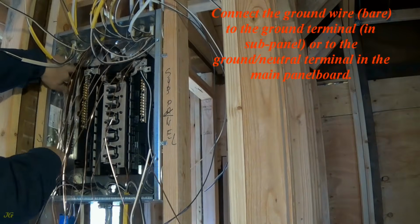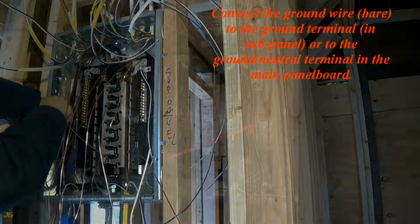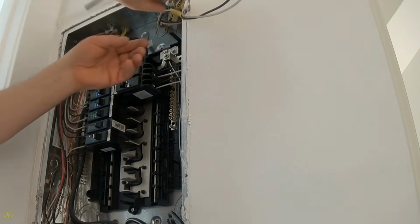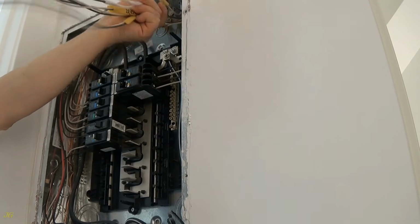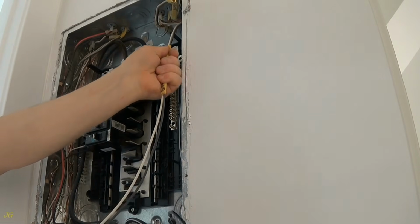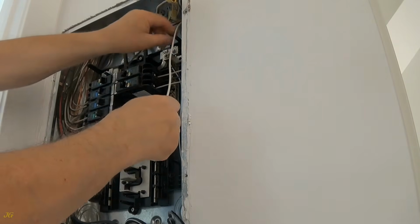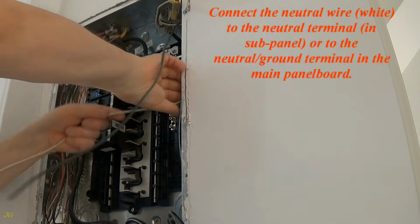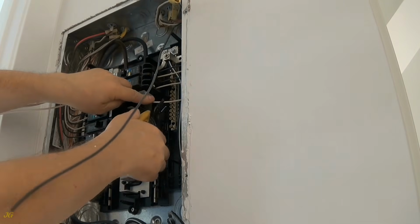Connect the ground wire, bare, to the ground terminal in a sub-panel, or to the neutral, ground terminal in the main panel board. Connect the neutral wire, white, to the neutral terminal in a sub-panel, or to the neutral, ground terminal in the main panel board.